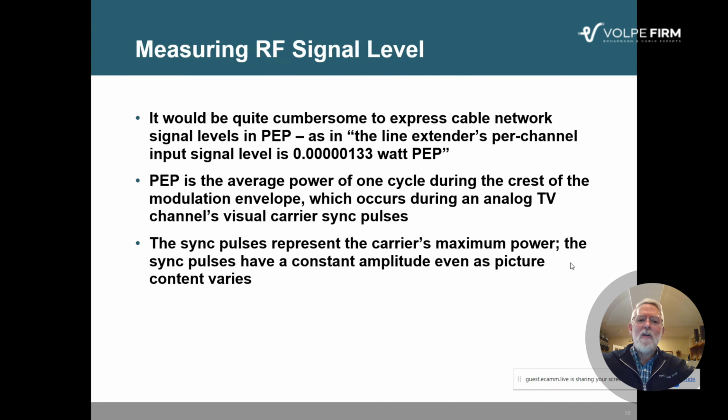Well, in a video waveform in an analog channel, a sync pulse is a waveform shape, if you will, that triggers the TV set in its scanning of the lines that make up the picture. If you remember looking at an old analog TV, it's made up of a whole bunch of horizontal lines. There's 525 of them in that picture, and they're actually interlaced. So there's 262 and a half lines that are drawn across the screen. The electron beam shuts off, goes back to the top, and then draws the other 262 and a half lines in between the ones it just drew.